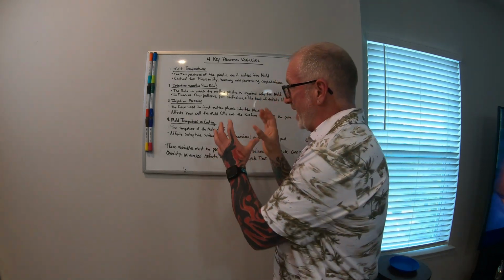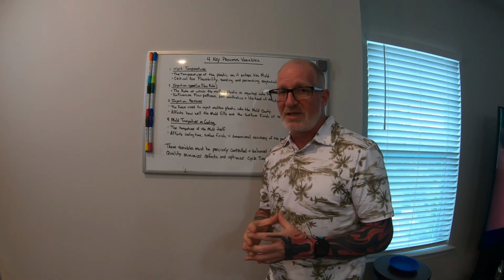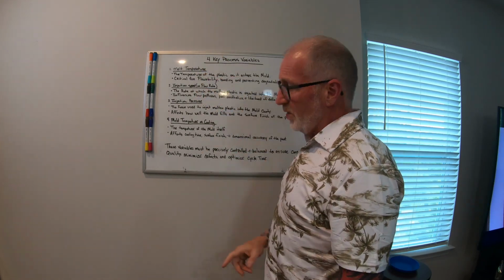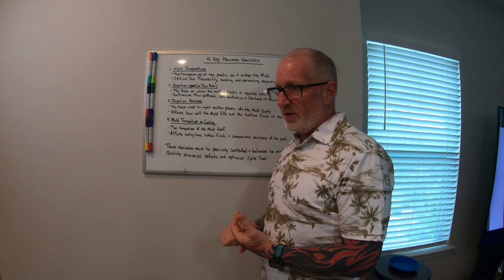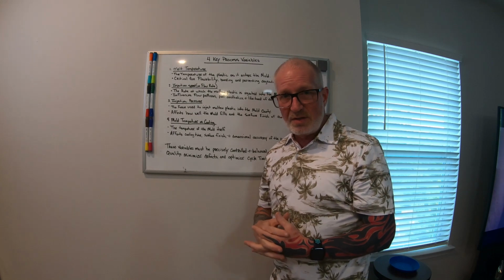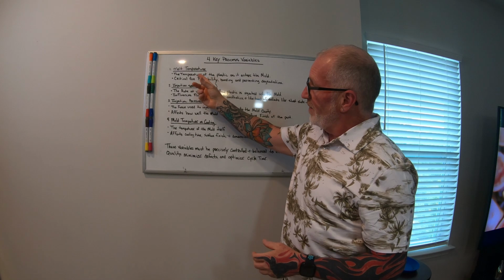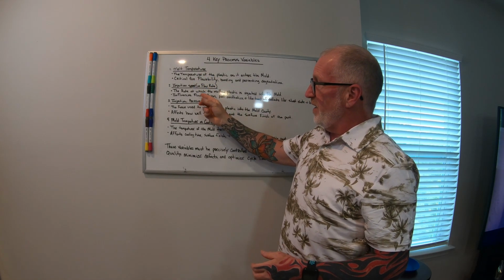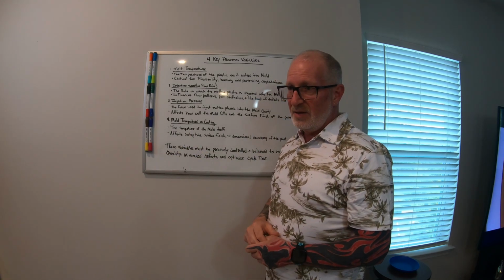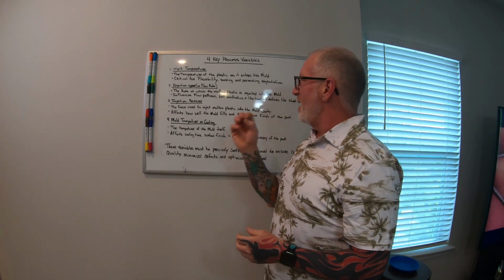Like I said, you could take this personally and use this towards a brand new process. Let's say you have a process, you come in, first thing I would do, check your melt. Make sure your melt on the barrel's good on that press, because that barrel on that press might be different on another barrel. So you could take this and go from one press to another, but I'd check the melt, make sure your melt's where you want to be. Then check the speed of the press, the speed of the material going in there. You can do what they call a linearity test. I think it's something like that. I'll have to look into it.